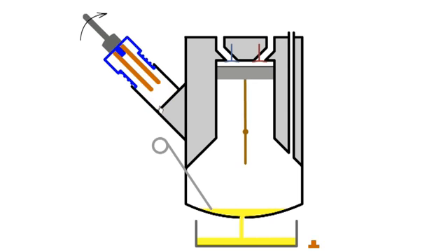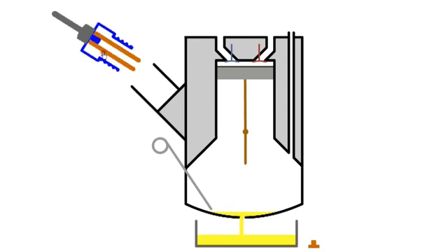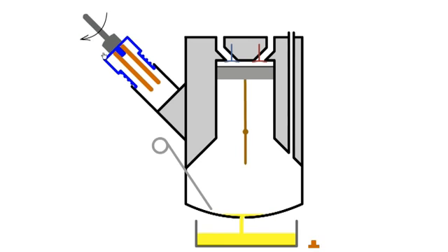When the filter housing is unscrewed, a hole opens in the housing and allows the oil in the filter to drain internally to the sump. The element contains no metal parts, it's manufactured from paper and plastics, and is suitable for incineration, capturing heat from the waste oil. The new filter and O-rings are fitted and the housing is tightened to the correct torque.